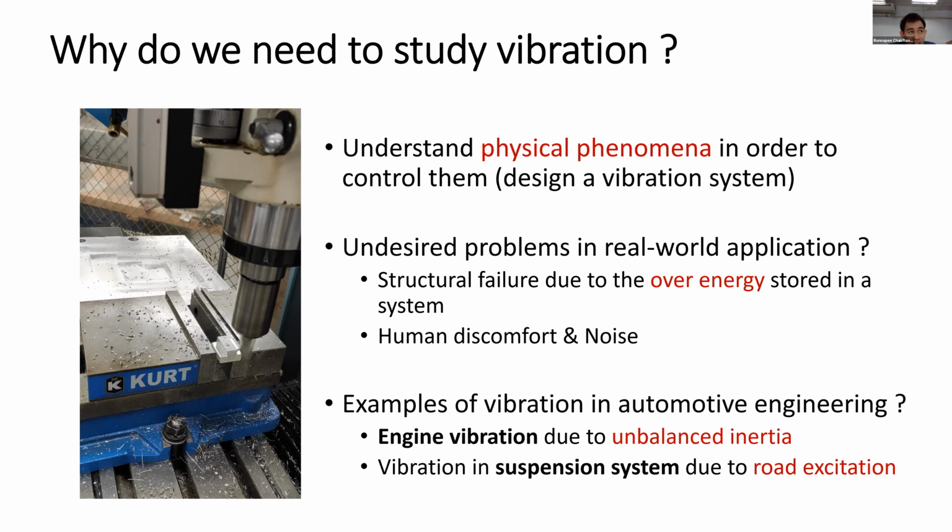For the engine vibration, in the beginning of the class, I drew a schematic to describe the unbalanced mass in the engine. And I mentioned that at the engine mount, engineers need to decide the suitable stiffness and damping coefficient so that we can isolate the vibration from the engine that is transferred to the chassis and the passenger.